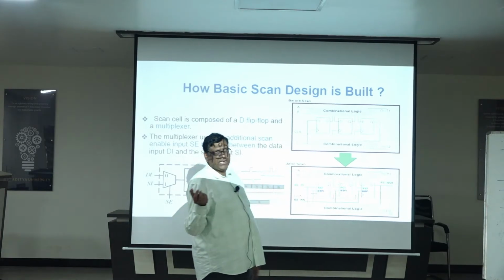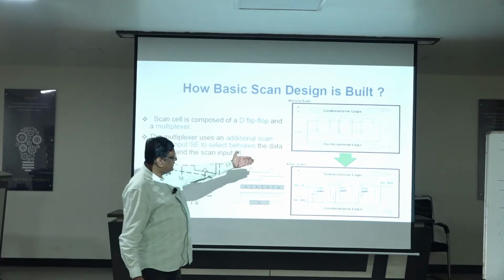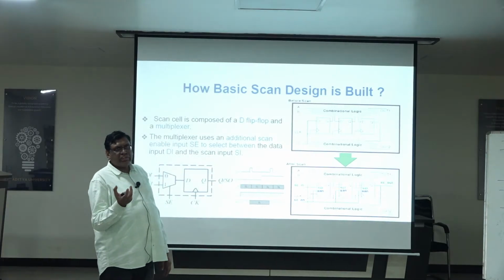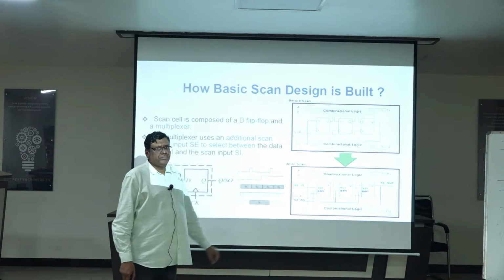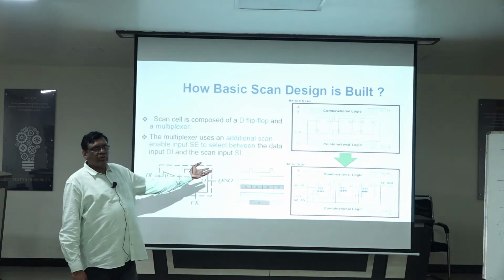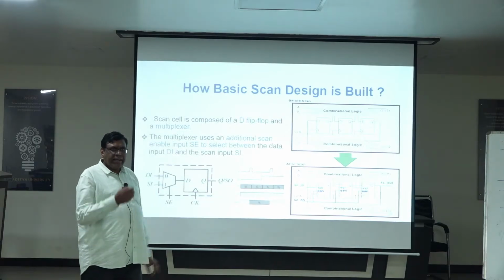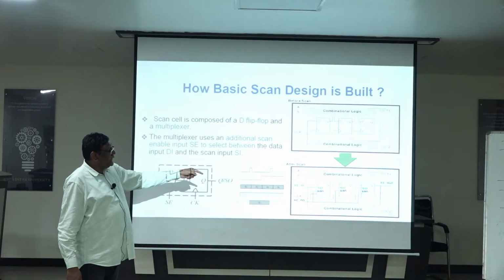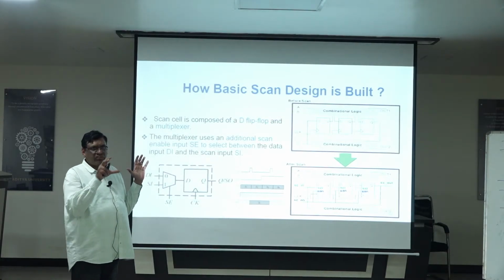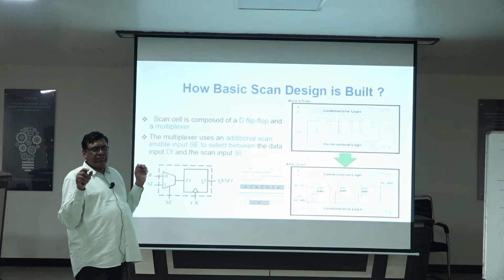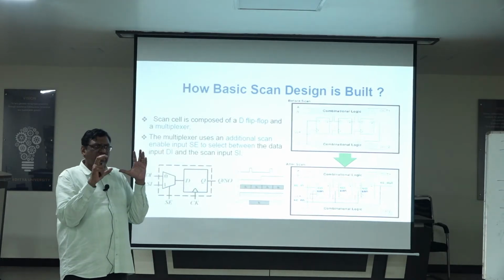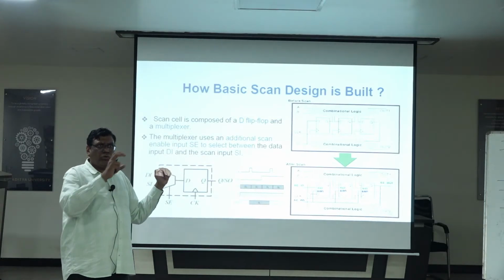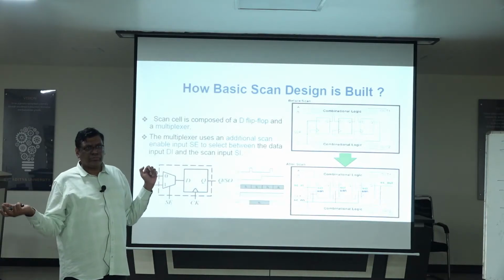We have seen an example. That example may be there inside this COM circuit. The output of the COM circuit will go to the flop. Again the data has to come out. How will it come out? While doing shifting, it will set the combinational circuit inputs. One example we have seen previously, inputs and outputs, a small circuit. Inputs will be set whenever you do a shift in. Output will be collected whenever you do the shift out.